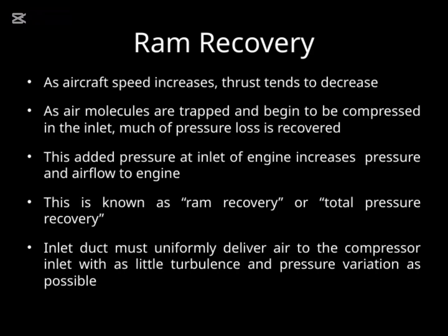As the aircraft speed increases, you'll notice that thrust tends to decrease slightly, which might seem counterintuitive at first. But what's really happening is that as air flows into the inlet at higher speeds, a lot of the pressure is actually lost due to various aerodynamic factors. However, as air molecules get trapped and compressed in the inlet, much of that pressure loss is recovered.